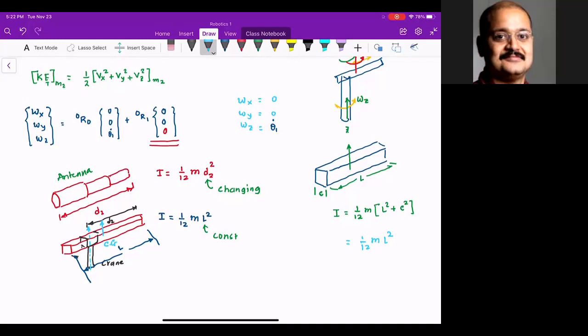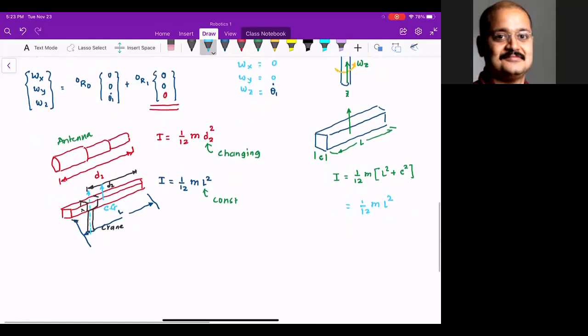If you don't follow, that's totally fine. So to answer your question, the reason we are solving the equation is that it is written at the center of mass, not at the center of rotation. Please note, the center of rotation is different. The center of rotation is at joint 1, but we are finding the kinetic energy at the centroid, or mass center, of link 2. Everyone understood this? I can derive a very nice half-page derivation on this, but I want you to understand that the equation I have written is correct.